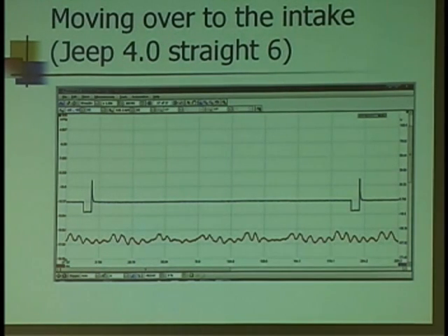Here's another pressure. Now this is using a pressure transducer. There's a difference. The sensor reacts to change but does not physically measure how much it is. The transducer physically measures how much pressure it is. And there are a bunch of them on the market. I personally use the Pico WPS 500 because the one transducer will cover ranges from intake manifold vacuum to 500 psi. Bernie makes the set. I think Snap-on has them. You can still even get the PV350 Fluke transducer from companies like AES. That will do just fine for you.